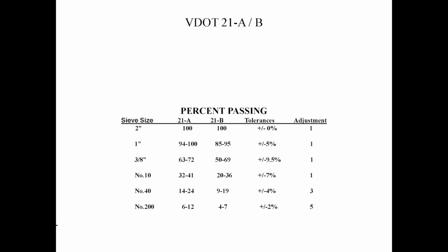So you can see, and again, this is a VDOT spec. This isn't their brand new spec, the 2016, but you can see that I've gotten myself into some real trouble here with what I did with that base material, just by not working that stockpile properly. I've cost myself some money or my customer some money. And again, when you look at the stockpile sample, bam, they nailed it. It was right down the middle.